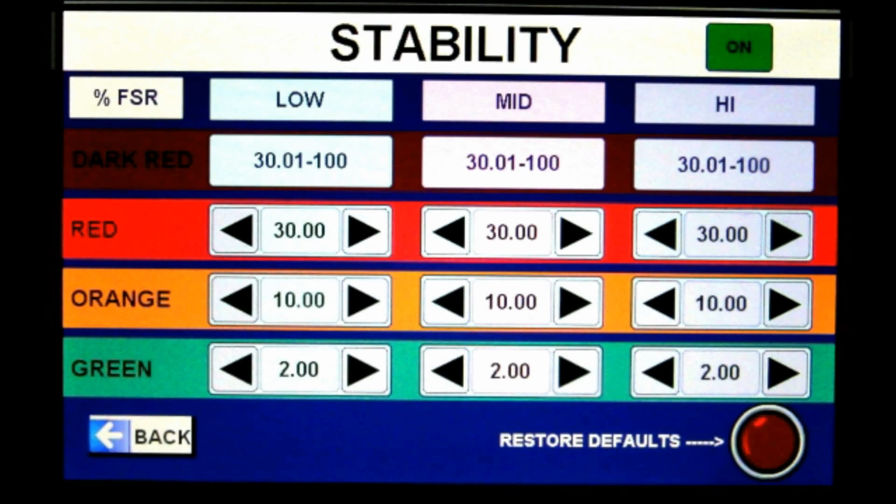The goal of this design was to allow the user to see the flow rate changing from the initial red font through the color spectrum, eventually settling on a steady green value, which would then allow the user to confidently record the flow rate. If later challenged as to what the stability criteria was, or how he determined that the flow rate was stable before recording, the leak rate tester may refer to the definition assigned to the green font in the stability screen in units of standard cubic centimeters per minute.